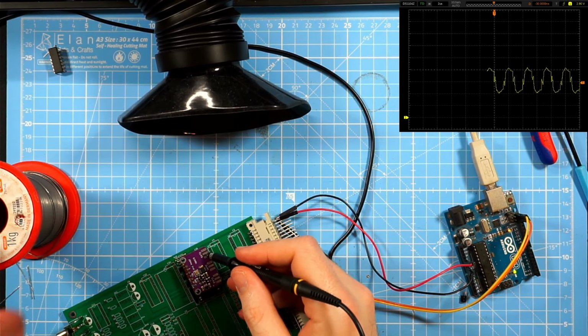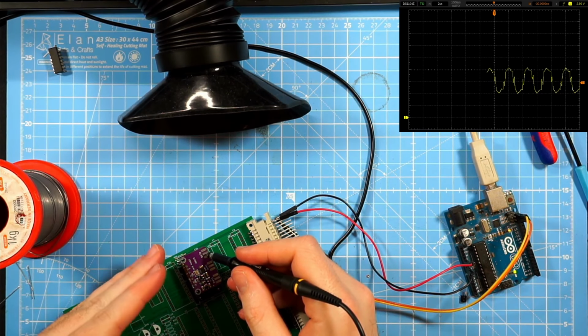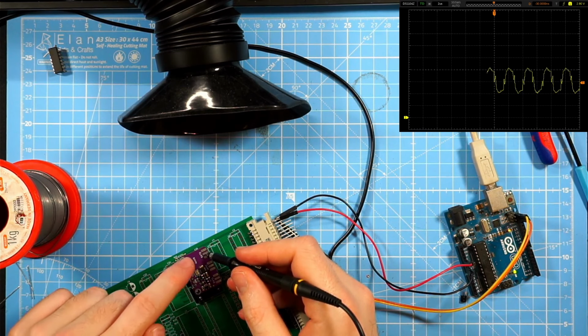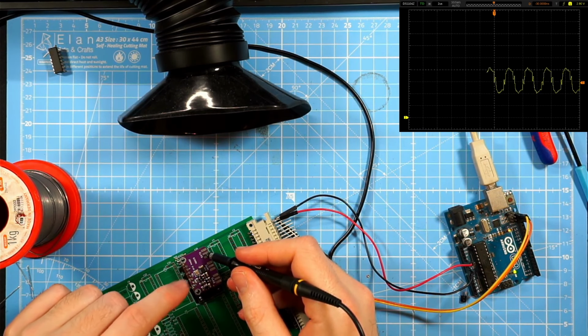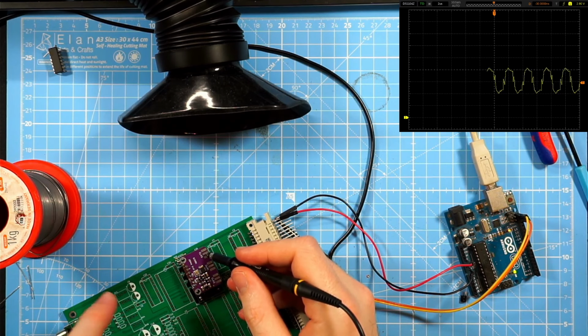It's still not doing what I wanted, and I guess for now I will just abandon this idea, use the voltage level directly out of the SI5351, or connect the outputs directly to the TTL inputs of those sound ICs, because the voltage levels should match high and low.